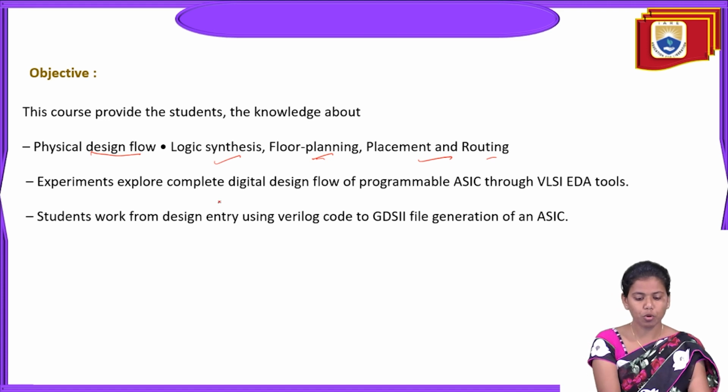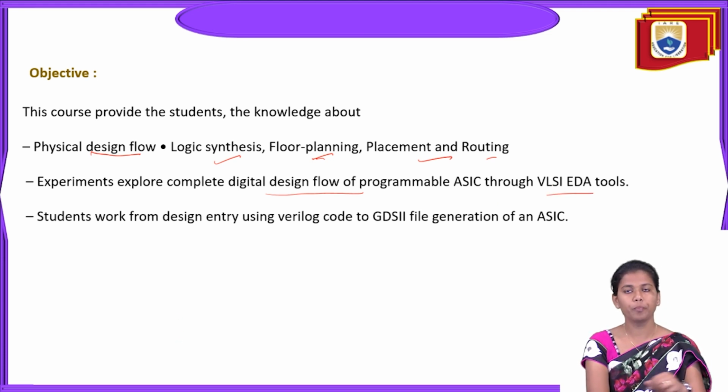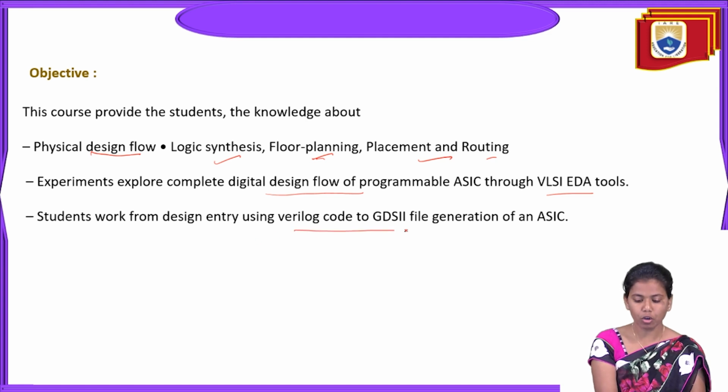The course also explores the complete digital design flow of programmable ASICs through VLSI EDA tools. After completing all this design flow, we will be able to know the digital design flow of programmable ASICs through VLSI EDA tools. With the help of the EDA tools, after designing, floor planning, routing, and all these things, we can execute the particular module or chip. Then students work from design entry using Verilog code to GDSII file generation of an ASIC.